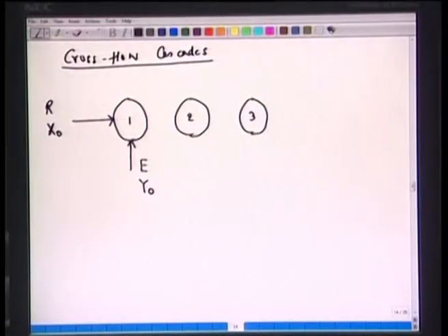Now, if you recall from our previous lectures, when we had the continuous contact process, we said that it is simpler to work on capital X and capital Y, which is solute free basis. All right. If you have binary components and only one component diffuses from one stream to another, then it is convenient to work on capital X and capital Y mole fraction as well as the molar flow rate on a solute free basis, because we realized earlier that operating lines in such cases become linear. So, our mathematical computation becomes simpler. We will also work here on solute free basis mole fractions and solute free molar or mass flow rates.